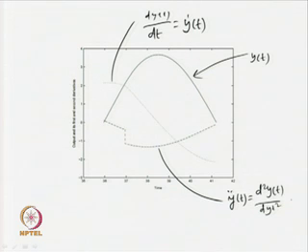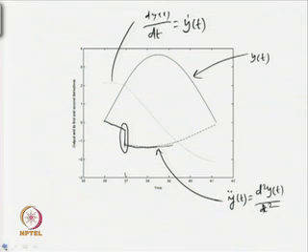dt square, sorry, dt square. In that case, from the second derivative of the output signal, it is apparent that the output signal has a discontinuity at this time. So, please keep in mind the discontinuity is shown by this: the output signal is not monotonically increasing or decreasing in nature, rather there is some discontinuity appearing at this instant. This shows that using this phenomenon, it is possible to estimate one parameter of the transfer function model outright, and that parameter is nothing but the time delay associated with the system dynamics.